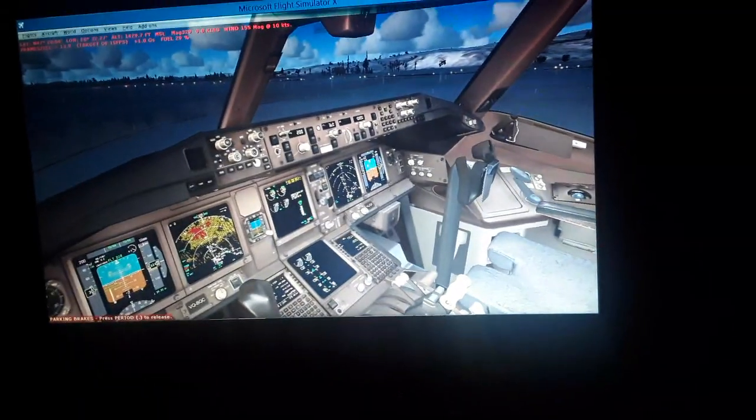And we're gonna have the ILS localizer frequencies tuned automatically or manually. So it's gonna be tuned automatically if we select from the flight management computer all the data for the destination airport and runway. In this case, it's the same airport that we have selected for departures. So we're gonna have the ILS localizer, the horizontal localizer, and the vertical glide slope tuned automatically using the flight management computer input or manually using the radio management panel. So you're gonna see how to do either way. I'm gonna show you both ways if we have time.